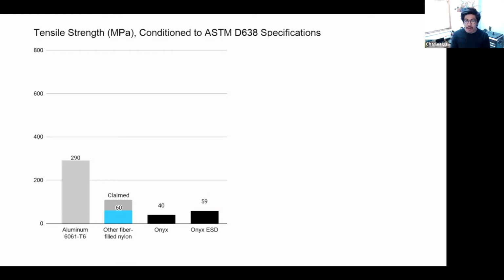It plasticizes it, makes it more plastic, which means it can absorb more impact, more energy before deforming. But that also means that it is going to be less stiff. So compared to an aluminum 6061, some people are claiming that they're nearly half the strength, right? There's the claim on their website, of course, says contains a carbon fiber, which is 5 times stronger than steel, but it's ultimately still a fraction of the strength of aluminum in terms of tensile strength.